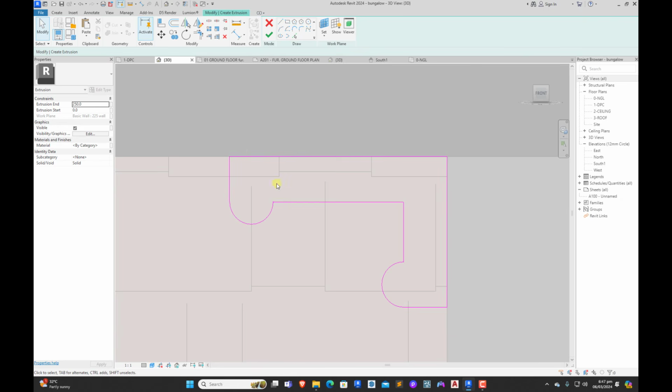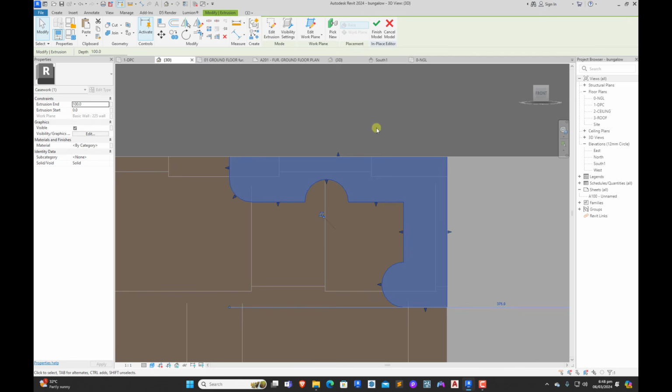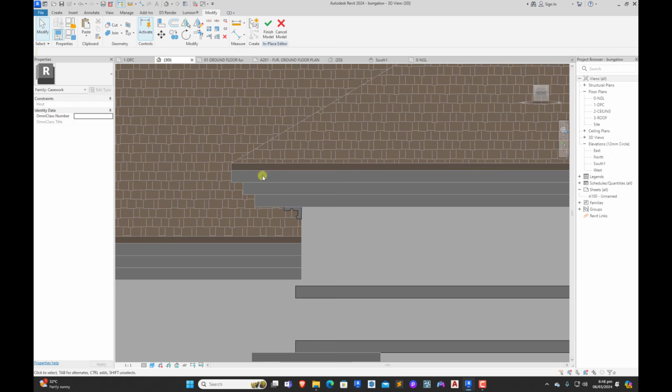Okay. Well, okay, wait. Let's do this. Let's make this way. Delete this. Let's just come here. Let's just curve here a little bit like this. Then let's make that inside this place. 30. Alright. Split it. Then we trim both of them. Okay. Then this should be 100, the thickness. Okay. So this is what we have.